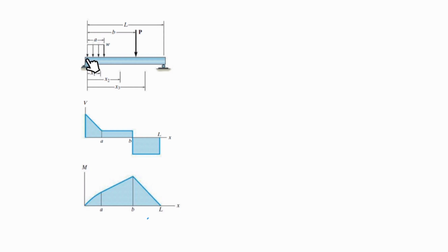What is the point of having these plots? We are interested in seeing the maximum value when designing. For example, this could be a bridge with a distributed load and a single force, and you are interested in finding the weakest point, or where we have the maximum bending moment. We design for this, making a structure with the same cross section all over the bridge, but the important point is where we have the maximum.